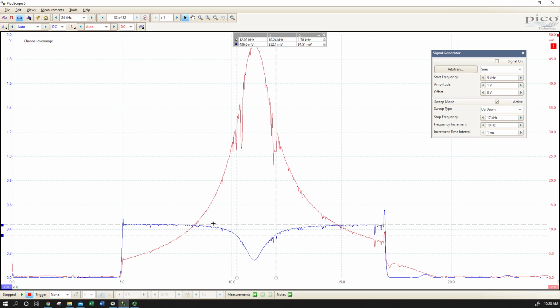I've got half the power. So basically here's my low power. This is my 3 dB frequency here. So this would be full frequency, no decibels lost. This would be the point on my curve, the frequency at which I've lost 3 dB or half power.